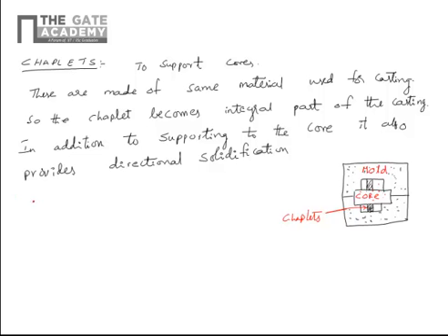Before providing chaplets to the casting cavity, they must always be thoroughly cleaned. So the chaplets have to be cleaned to avoid a weak joint between the molten metal and chaplets.